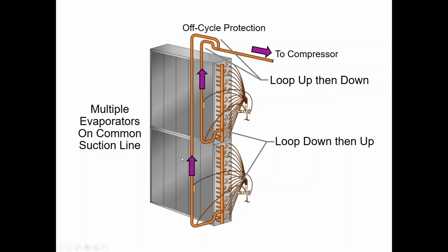The purpose of that is, if we brought the top coil on first, think about all your condensation. It's going to run down onto a warm face coil, and it's not going to hold the condensation. You'll get condensation carryover, blow off, whatever you want to call it. So that's why we always have first on, last off on the bottom in split face applications.